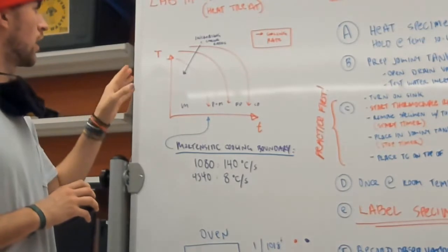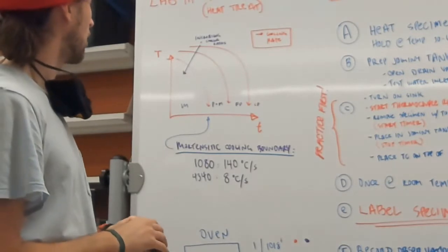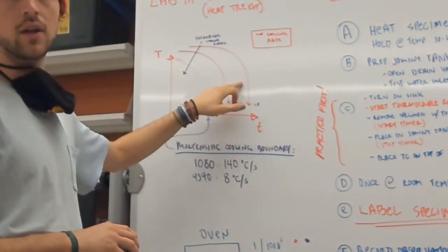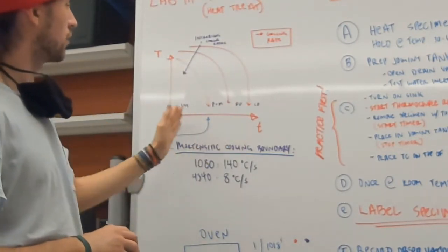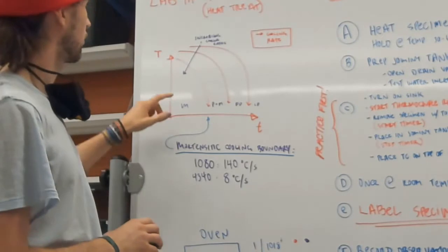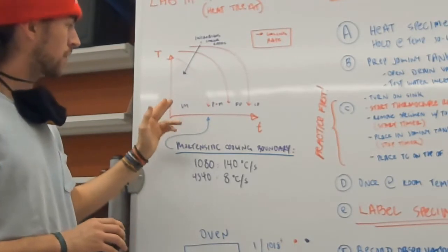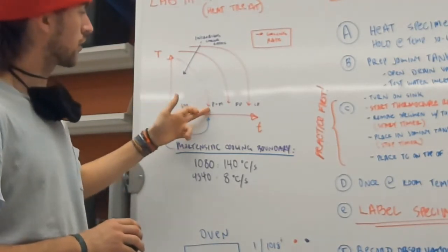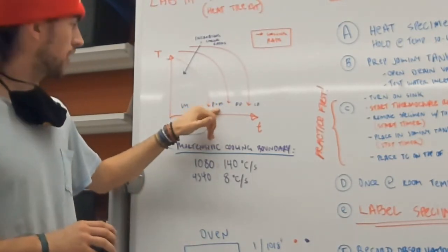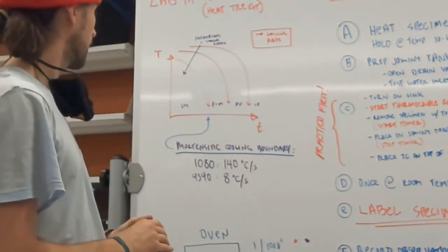What I want to talk about is the cooling chart for steel. They have these charts for all different kinds of metals, and for each grade of steel, there's a different chart. Here we have these lines of constant cooling rates, and the faster you cool your steel, the more martensite crystal structure you'll have. There's a critical cooling rate where faster than that, you'll have full martensite, and at slower cooling rates, you'll have different crystal structures. So you'll have a mix of martensite and pearlite, and then as you cool slower, you'll get different crystal structures.